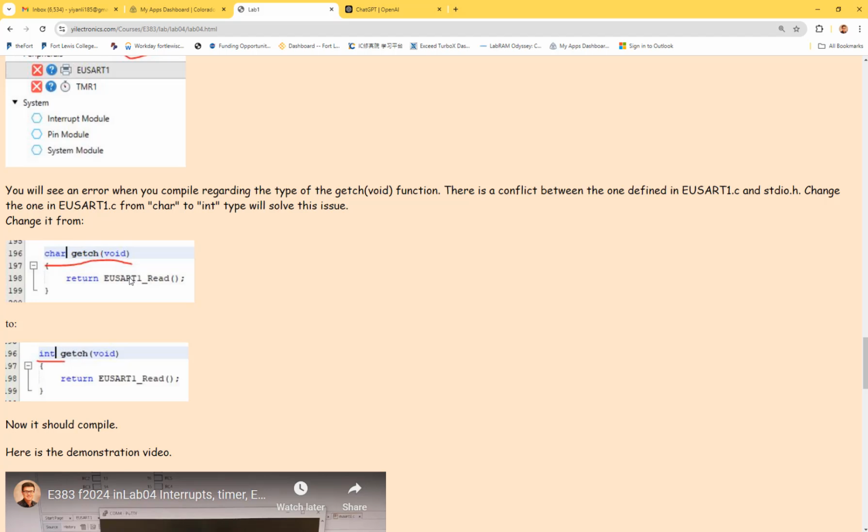It's just serial communication. When you plug your embedded system into your USB, it's communicating with your laptop using UART. This is a slightly different version of the regular UART, called EUSART, an enhanced universal synchronous asynchronous receiver transmitter. It's still a very similar UART protocol. I didn't dig into the details of this protocol, but I believe it's very similar. So it's just a UART.